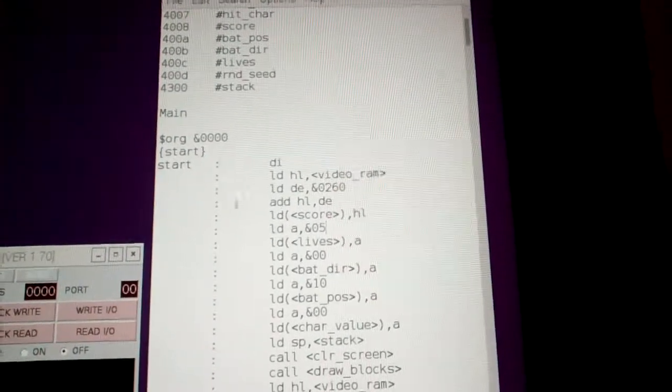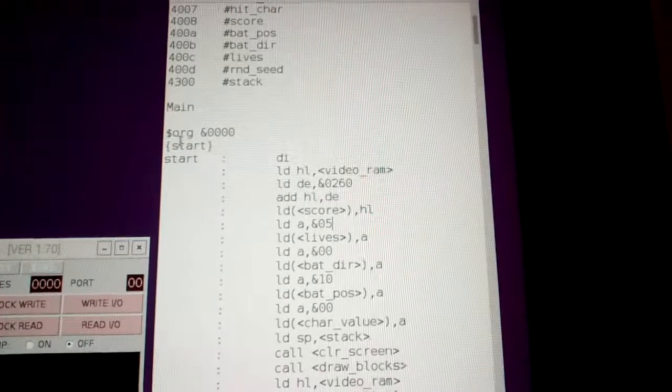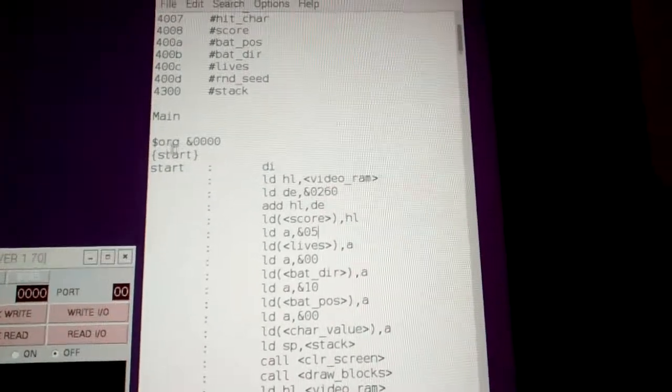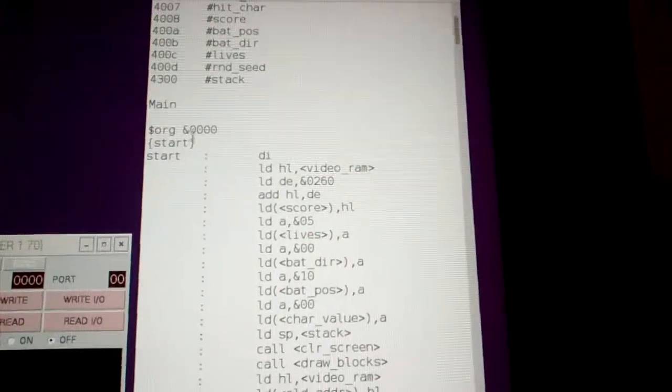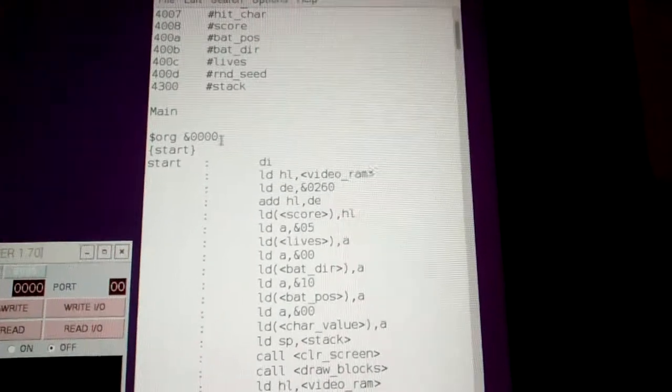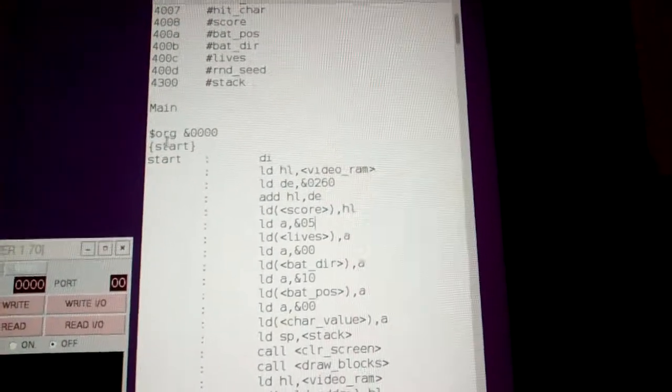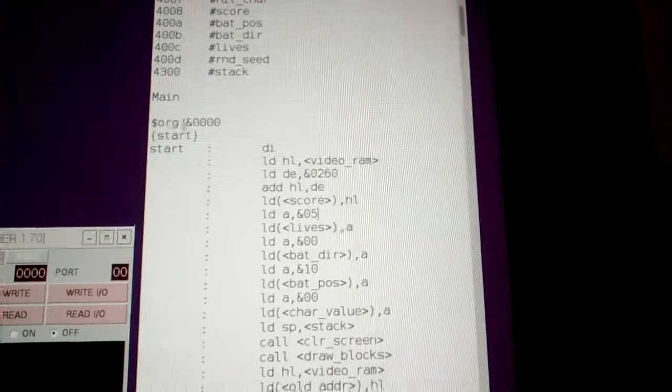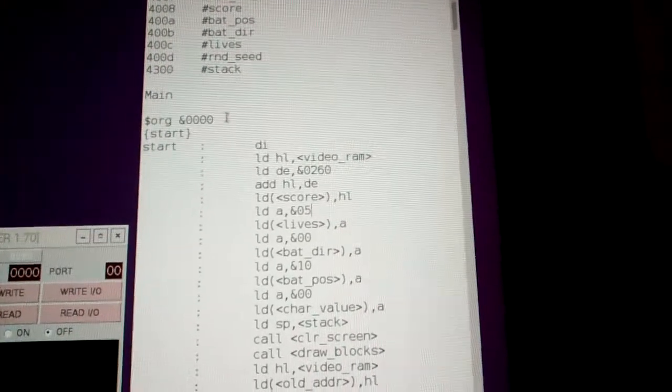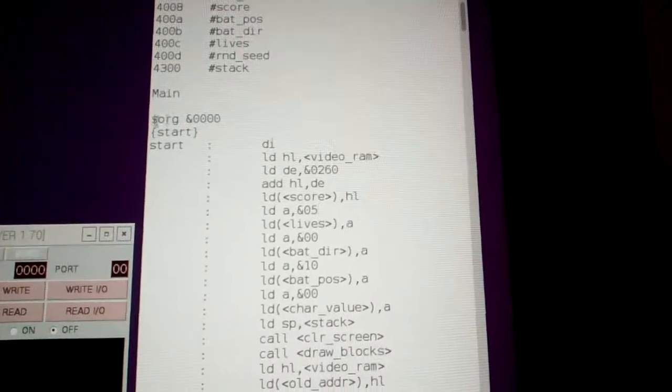And the other important things are you have things like org, for example, dollar as a command. So $org and then a space and ampersand, that's the address. So org is the start address. So every time the tester reads one of those lines like that, it will actually set the address of the tester to that address.